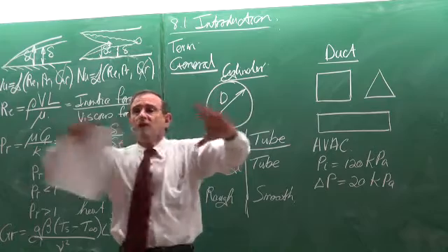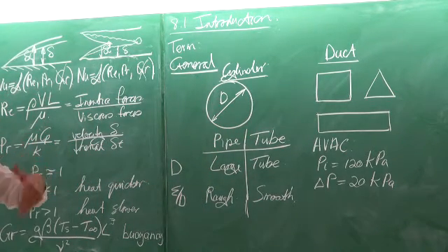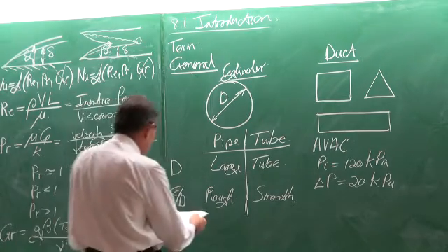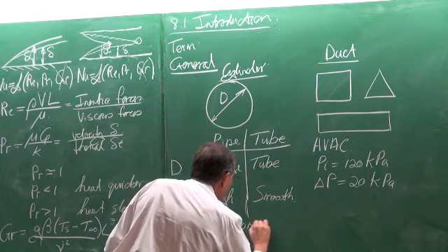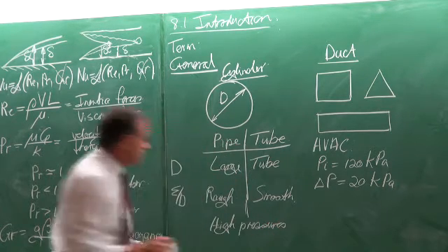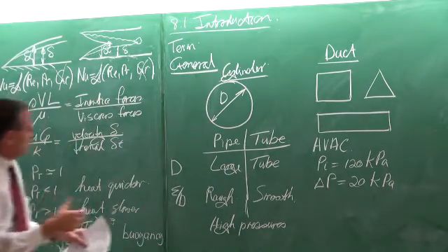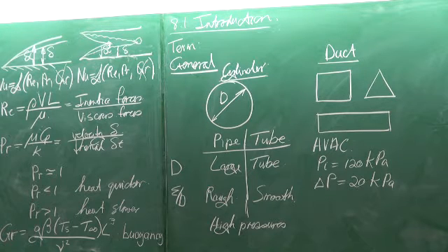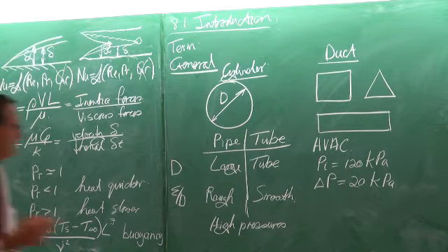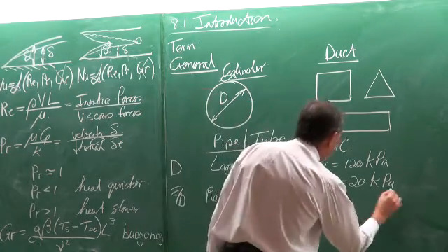Why? Because usually they are very big. And because the area is so large, the forces are very, very large. Okay. Now pipes normally can take very, very high pressures. So in pipes we will normally get fluids, and a geometry like that can take very, very high stresses, in the order of megapascals, very easily. Okay, so megapascals, while here we are in the order of kilopascals.